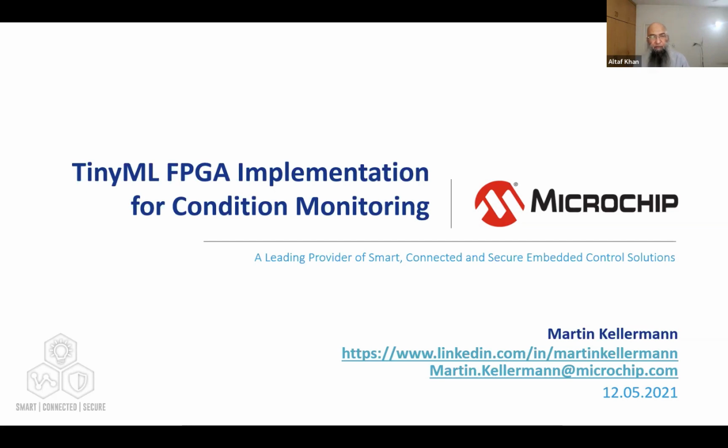If you use the standard approach, for example, ARM has that approach that you take a complex network and then you apply a set of steps to it to simplify it, like quantization, like getting rid of some neurons or some edges. We don't do that. We do everything during training. So our training has two objectives, not one. The dual objective is, number one, minimize the error, and number two, minimize the complexity. So what we get at the end is that C code that you see.